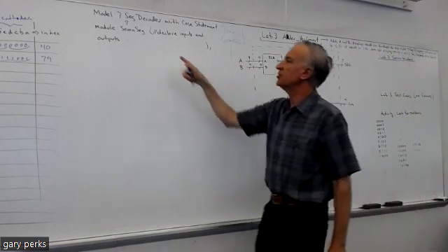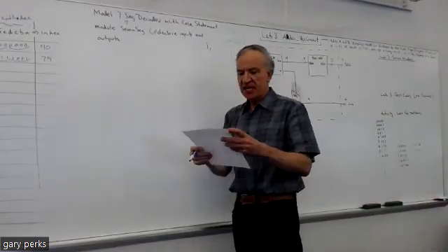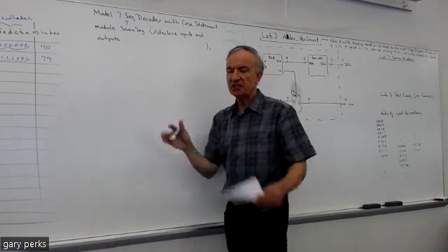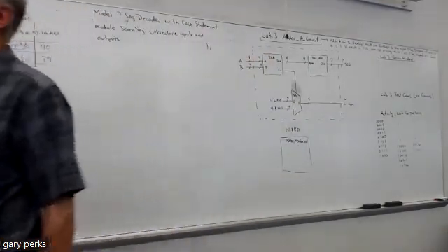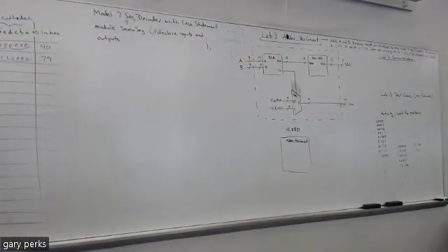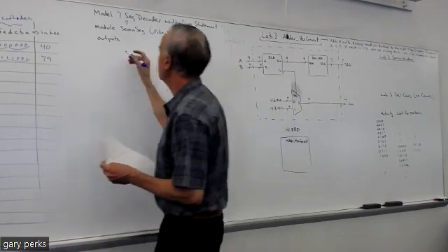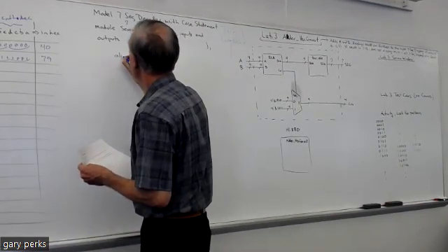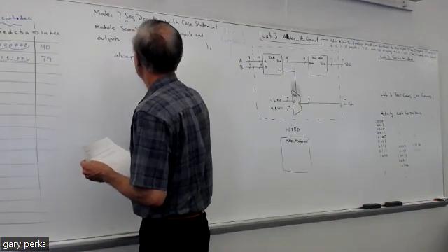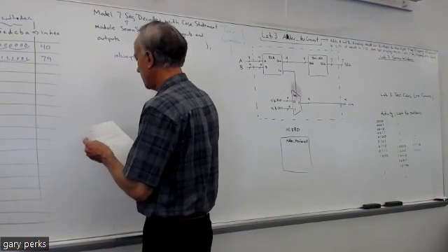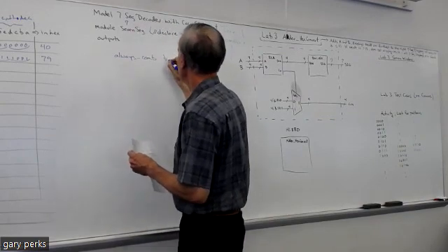Okay. So you declare your inputs and outputs, and then just like with an if statement, a case statement has to go within an always_comb block. All right. So after you declare your inputs and outputs, you have always_comb, and then you would need your begin.